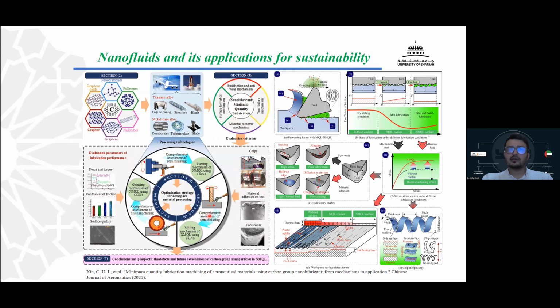So when you do grinding and cutting of these devices, for example, instruments, the easy idea would be given here. So this is without a coolant when you do grinding, for example, working on a piece. And this is with a minimum quantity lubricant coolant. And this is when you apply nanoparticle minimum quantity lubricant. You can see clearly that it helps in reducing the wear and tear, improving the performance, and even the lifetime of the cutting tools that you're using.